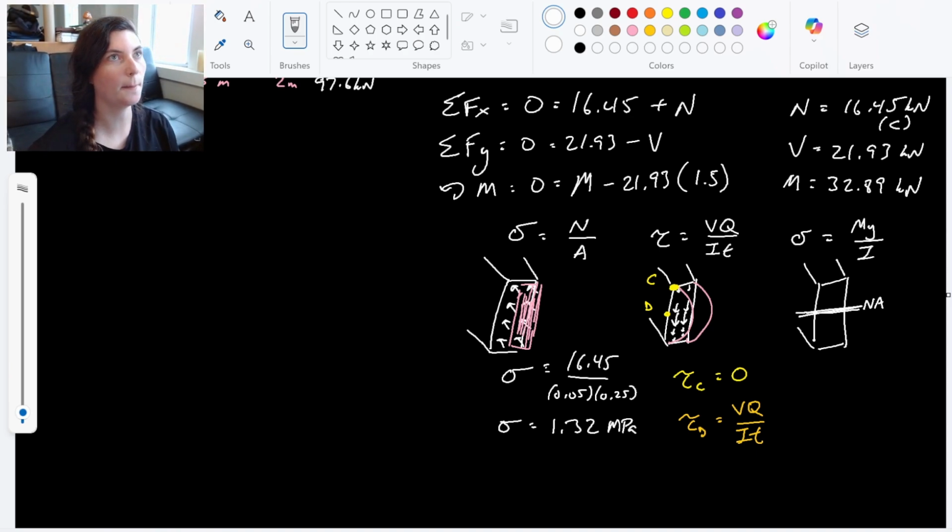So what that looks like is that our highest amount of stress is happening at the ends, right? There's a high amount of stress, and then it's smaller and smaller until we hit the neutral axis, and then it comes back out. So it's going in, here is being compressed, and then all of a sudden it switches at the neutral axis and comes back out. Gets bigger and bigger until we hit those edges again. So there's C, and D is on the neutral axis there.